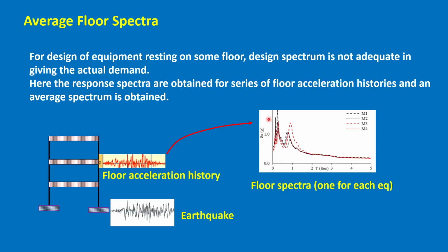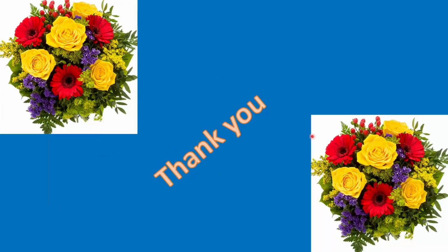So we have drawn the acceleration response spectrum for the floor, and we have considered several earthquakes here one by one, so that we got several response spectra for the floor, and you can take an average of all this and use that for design purposes for the foundation of the equipment resting on the floors.